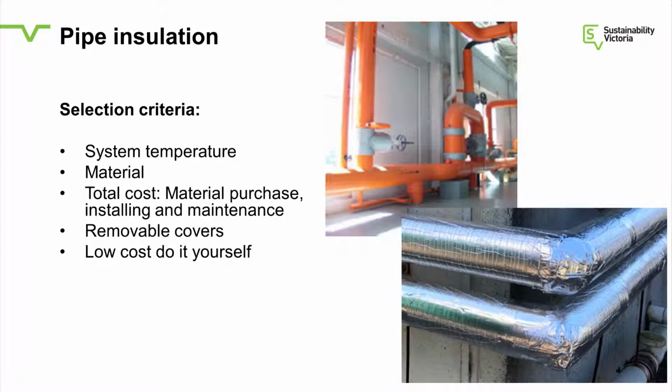That's typically got a payback of 2 years or so. So it's a pretty good idea, and I know quite a lot of the large industry are looking at that very seriously, are putting insulation on valves, and some of your clients have done that, and I think it's been quite effective. So that's quite a good initiative, not that complex, and is starting to happen in quite a lot of industry where there's a lot of valves uninsulated, a lot of flanges uninsulated.